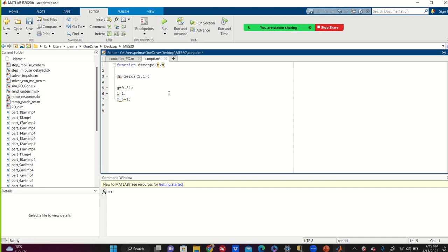Okay, whatever. So, and oh, dm. Okay, and so now dm1, remember, is m2, and dm2 is u, the controller that we designed, minus omega n square multiplied by m1, where the natural frequency of the system omega n is sqrt of g over l.